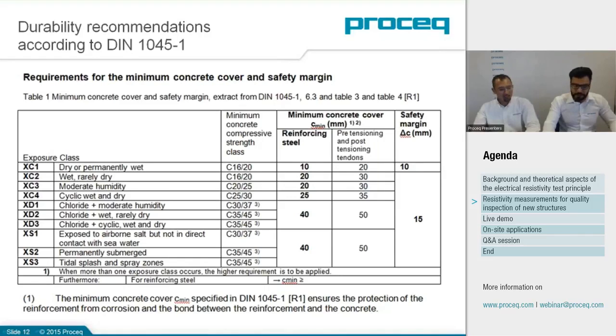Of course. What is mentioned later, the British standard, is more or less the same, apart from some numerical values. We have increasing aggressiveness of the environment as we go down that column. While it's normal to consider dry concrete a safe concrete, and to think that if it's in water and I'm fearing rust, that is dangerous, it's slightly more complicated than that. Without going into too many details, corrosion, in order to progress, needs at least moisture to carry the electricity, and oxygen, which is a fundamental reaction. So you get a chemical reaction. Obviously. Absolutely.